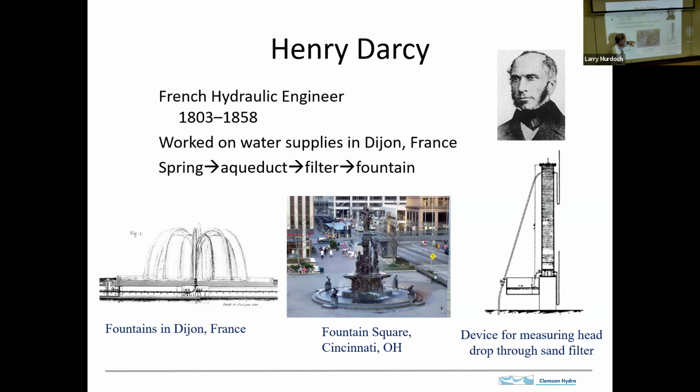And then they would put it through a sand bed, and that would filter out the colloids, the particles, and a lot of the bacteria too. So it took out a lot of the pathogenic bacteria. With that fairly simple method of water treatment, they were able to make the water a lot healthier to drink.